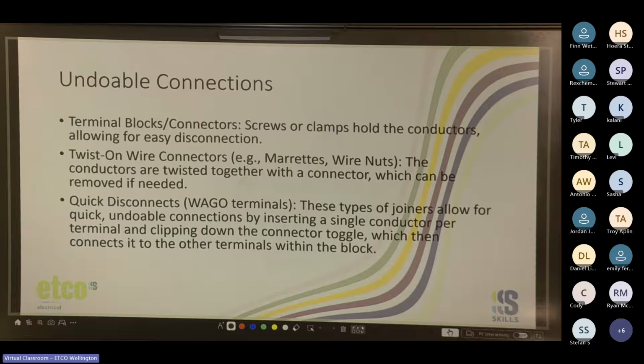I know guys who are like that. But what I will say is a chocolate block connector will melt before a Wago will. They've done tests on it, and the Wago will withstand well over the voltage that they're rated for. But each to their own. For me, they're a little bit expensive for day-to-day use.